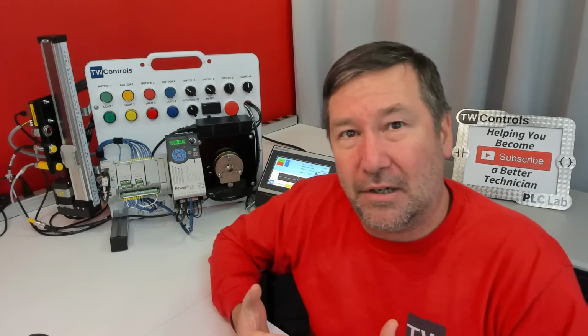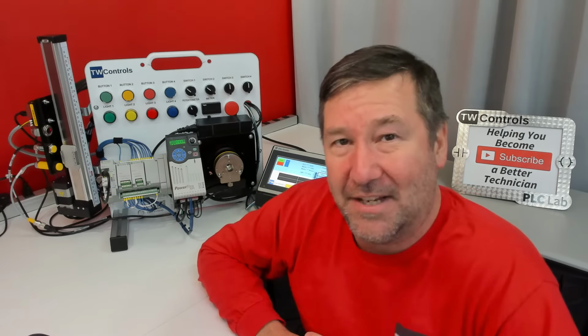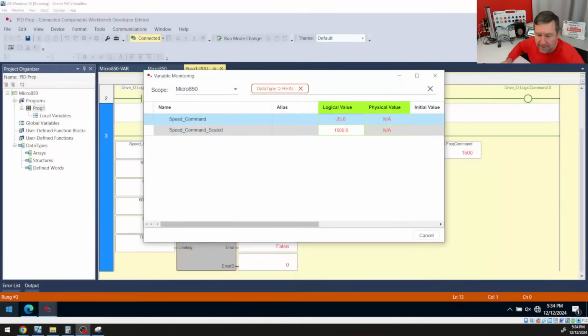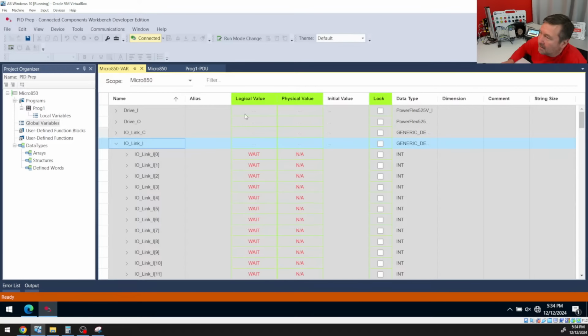Now, there's a lot more involved in the IO-Link scaling because, well, we do have a video series on IO-Link, but it's not in this fast track series, so we need to slow down a little bit and talk through some things and make some observations. So if we go over here and close this out, and double click on our global variables, and we hit the arrow by IO-Link:I, well, we have a lot of them here, and I had to do a lot of scrolling, and anybody who's been in class knows how I feel about scrolling. So I want to know, where is this encoder at in this?